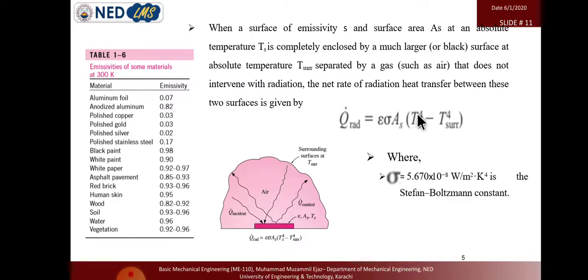So we cannot apply the temperature in degrees centigrade. In conduction and convection we solve numericals with simple degrees centigrade, and it does not affect the answer, because adding 273 nullifies in the difference. But when we apply the power 4, it will not nullify the effect. So in this radiation formula we always have to place the temperature in Kelvin.